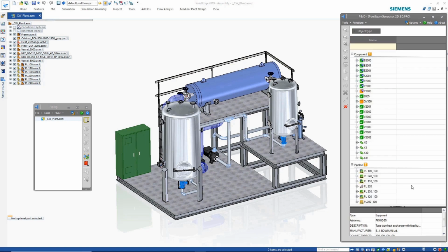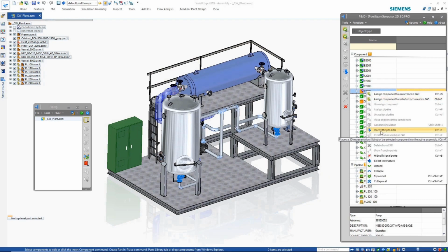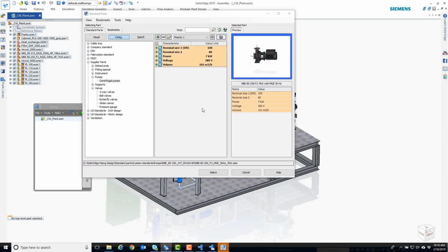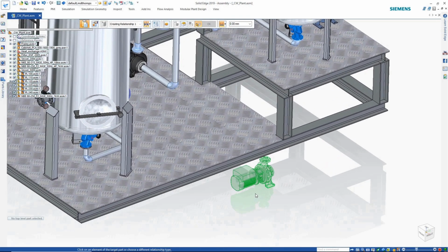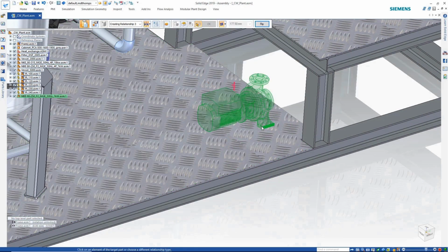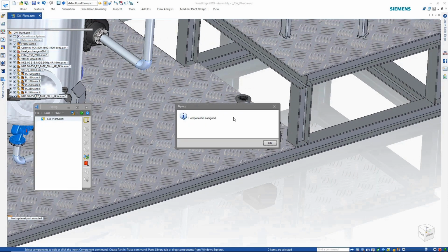What I'll then do is let's select our pump. And if we right click on it, and we then select place fitting to CAD, and then we just select where it will actually go, and we see all the specs about it here as well. What's very nice is that we want to place this pump maybe there for the moment, but we actually want to move it onto the grid there. And what's quite cool is that there's even a mounting like position available for the pump as well for us to use.